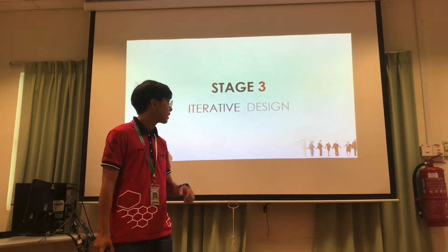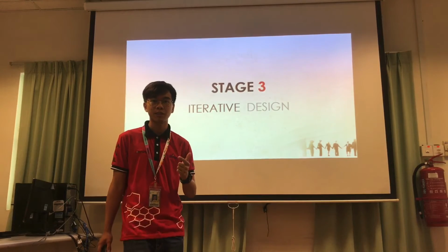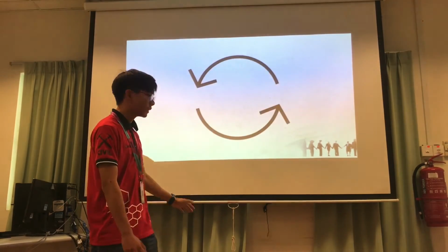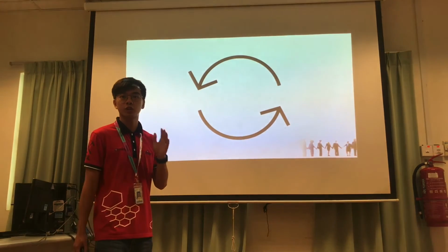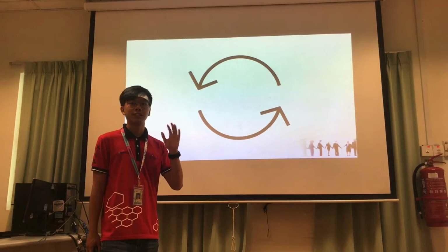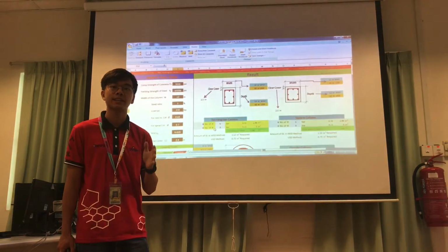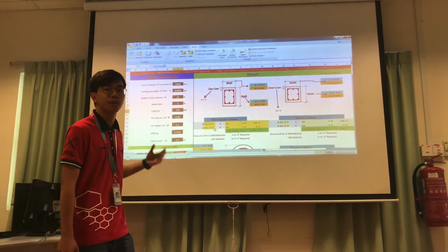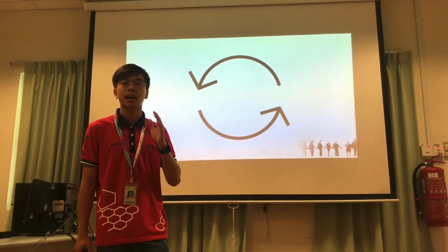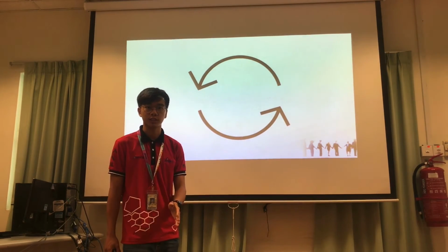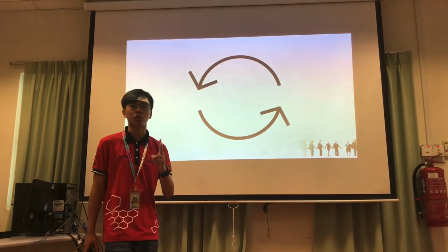Next, the third phase is iterative design. Iterative design is fundamental for the design process and inevitable for the process of structural design. This phase is cyclic, repetitive, and also evolutionary. Based on initial sizing, the information of the straining actions on the element is obtained, and the design process is eased by using a spreadsheet or software. Then the analysis model is modified to the new dimensions obtained from the previous design. This analysis is then repeated. In the repeated analysis, new internal forces are obtained, thus the design is revised again based on the new forces. The iterative process is repeated until the element design is the same in 2 following iterations.